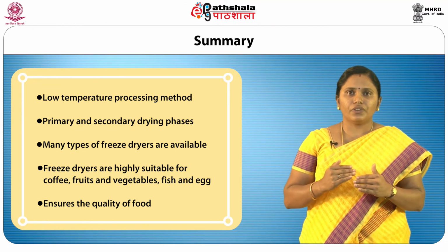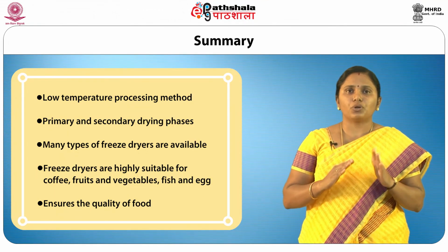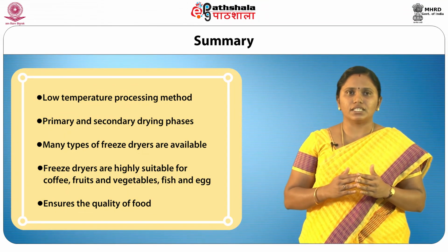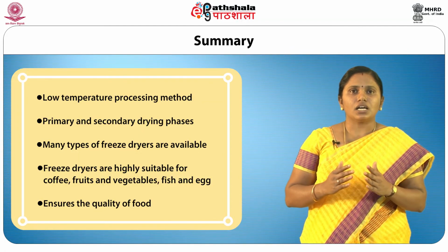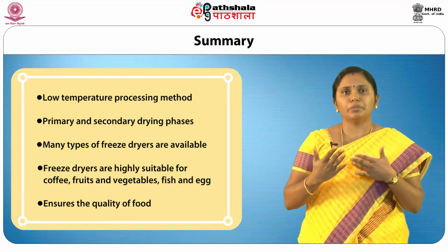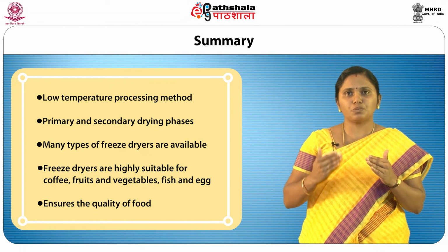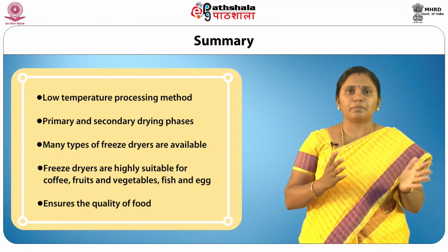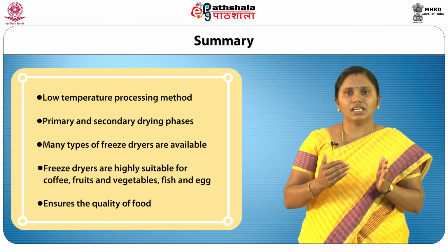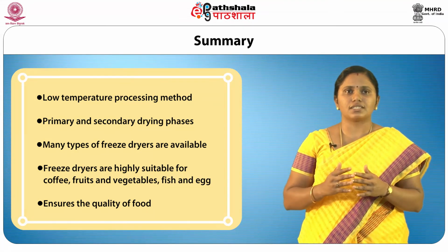Low temperature preservation ensures the quality of food materials, and freeze dried products retain the shape, color and almost all the nutritional qualities. Rotary dryers are highly suitable for granulated food materials which require proper mixing during drying. The rotary dryers are applicable to continuous processes and larger production capacity products. Rotary dryers are not suitable for sticky and sensitive materials such as sugar crystals and perishables.